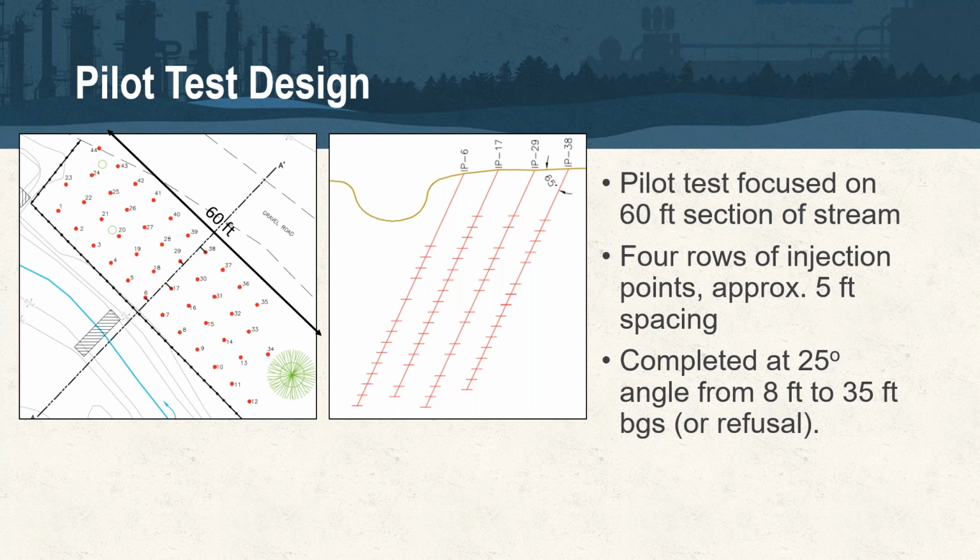Now we do have the injection system that we use for our bedrock sites, which has pretty high flow capacity, up to 300 gallons a minute. And so we have used that selectively on some overburden sites where we are working deep and we can really push the radius of influence. So maybe in that extreme case, if you're bringing that unit out, maybe you're working on a 15-foot spacing. But in general, we're on that 5 to 10 foot range.